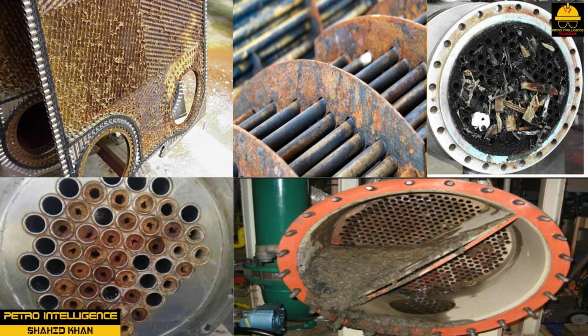An exchanger's fouling resistance depends on the type of fluid being handled, the amount and type of suspended solids in the system, the exchanger's susceptibility to thermal decomposition, and the velocity and temperature of the fluid stream. Fouling can be reduced by increasing fluid velocity and lowering the temperature. Fouling is often tracked and identified using checklists that collect tube inlet and outlet pressures and shell inlet and outlet pressures. This data can be used to calculate the pressure differential, or delta P. Differential pressure is the difference between inlet and outlet pressures, represented as delta P.